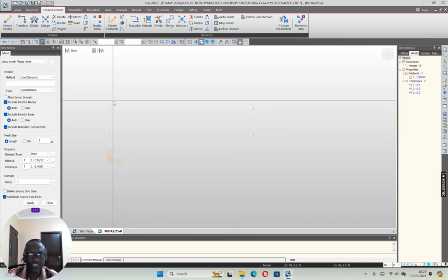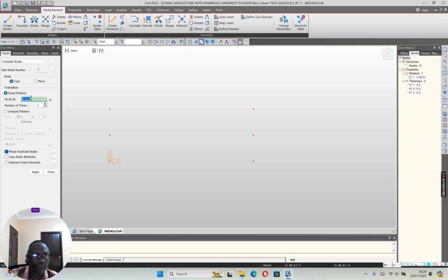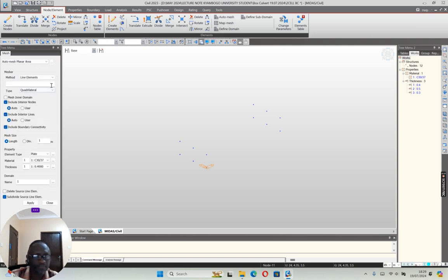So now I have, let's say this is the bottom. So I offset this. I translate the nodes in the Z direction, and it's about 500 thickness base and 500 top. So that means it's 3.5. So 3.5 center to center, I put my 3.5. Positive means I will go up. So once that is done, you can see I have my extent of the center line of the box.